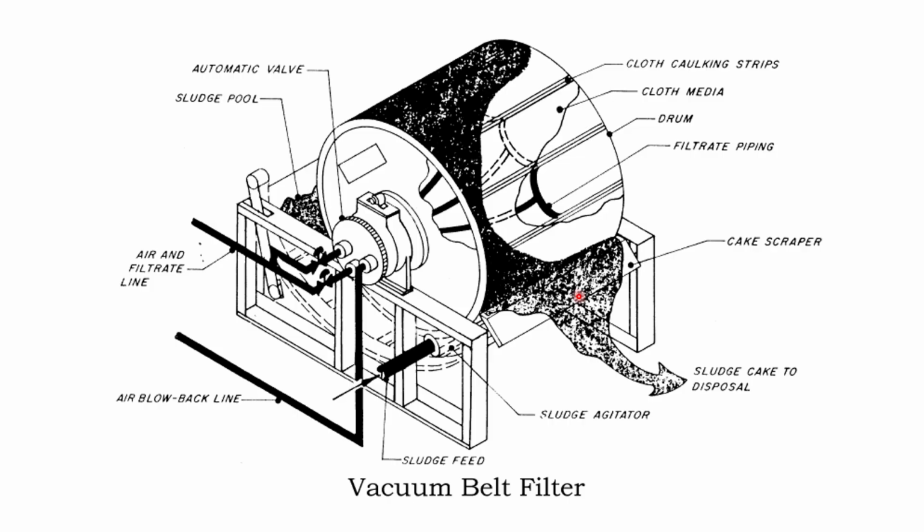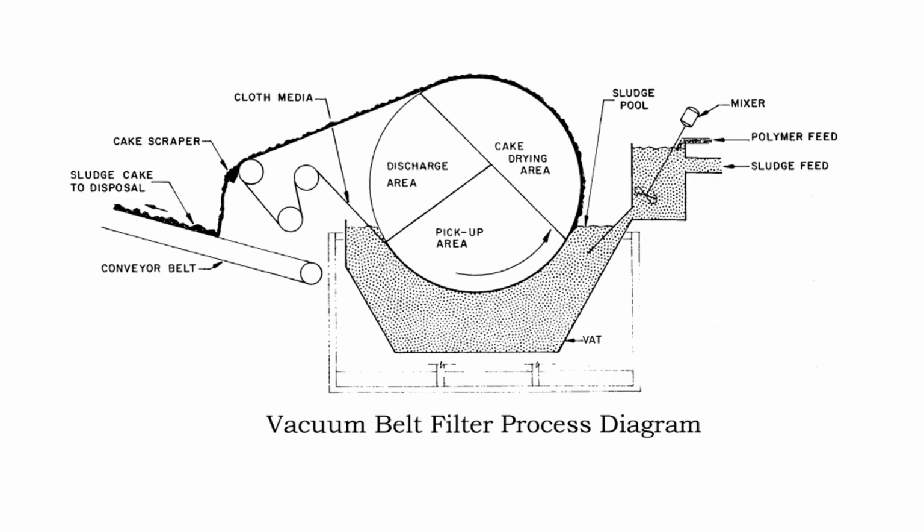And again, that centrate or filtrate's going to go back to the headworks, and the solids are going to get pumped out. Okay, that's all you're doing. Think of it as a big roller that the vacuum is helping with, but that's all it really is. And you've got this cake being formed, and the scraper takes it off, and that sludge cake goes out for management as biosolids. Okay, and that's the side view of it.